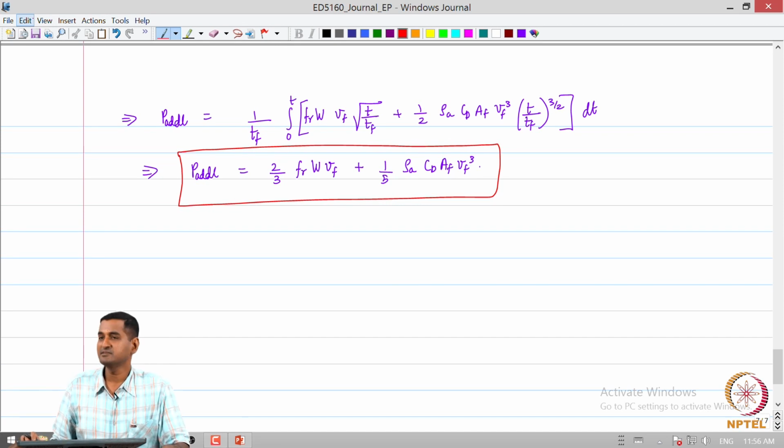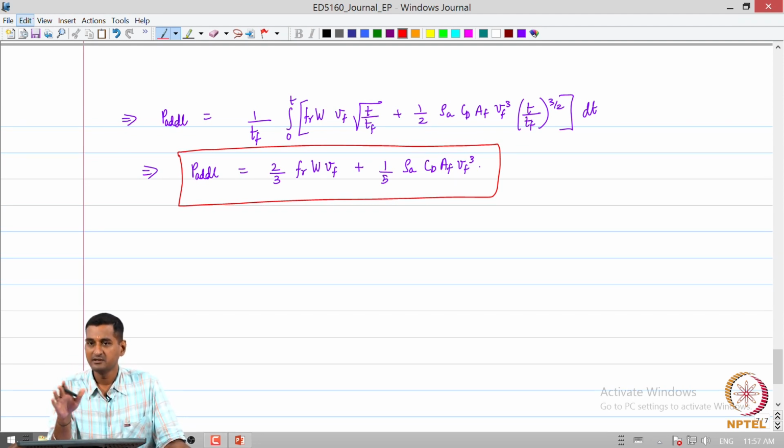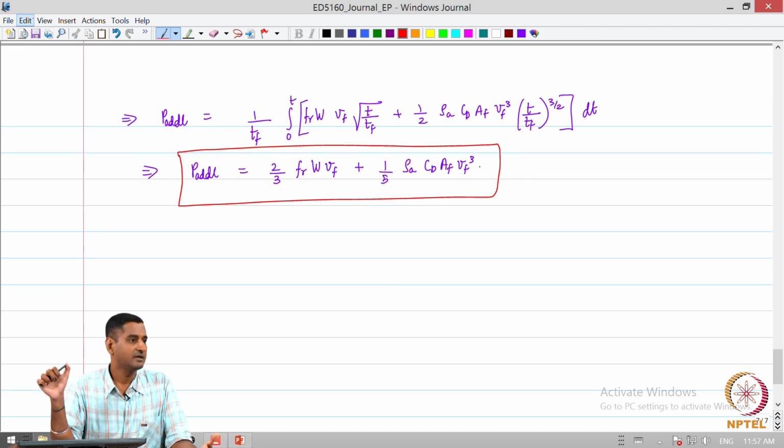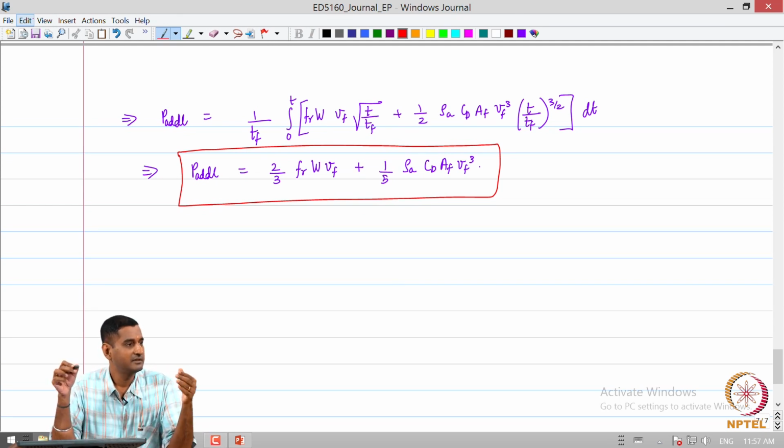So, what do these simple expressions provide us with? They provide us some tools to calculate the torque and the power requirements for satisfying these various vehicle performance requirements. So, the impact of these derivations is that if we are given some basic vehicle performance requirements, we could use these expressions to get the corresponding motor power rating.